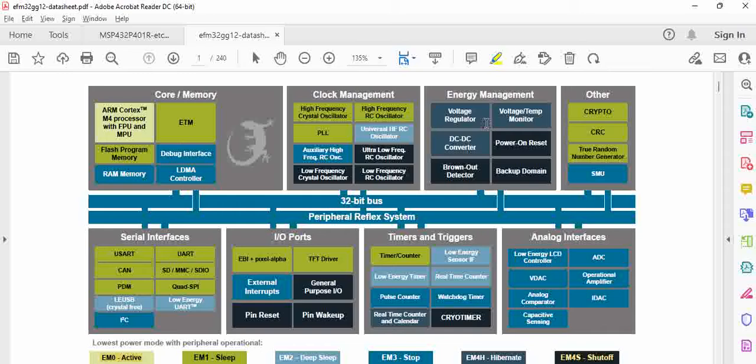And definitely this is very important. If you have a very low power consumption board, a small board that needs to be designed, and you don't want to use an external LDO for your application, and you just want to take some 5 volts and generate the required rails, this is the one to go for. And you save a lot of cost as well, because you need not add an additional LDO outside to generate the 3.3 volts for the microcontroller.